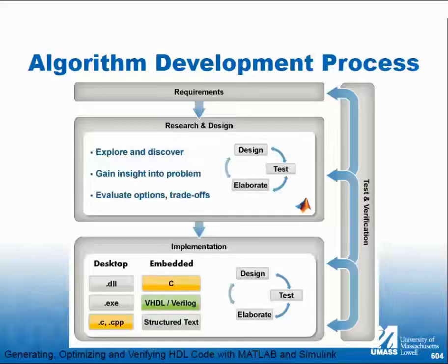An autocoder is something that does the same thing, but in the software world. So what autocoder does is you write your Simulink MATLAB definition of the design, you press a button and it puts out C code, right? So it's something you'd run on a processor. In the FPGA ASIC world, a lot of times we're looking to produce HDL, so VHDL and Verilog. And that works well too, and it actually does produce this code.